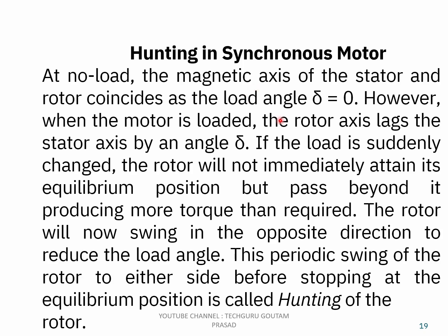So what is hunting in the case of the synchronous motor? At no load, the magnetic axis of the stator and the rotor coincides as the load angle delta is 0. However, when the motor is loaded, the rotor axis lags the stator axis by an angle delta. And if the load is suddenly changed, the rotor will not immediately attain its equilibrium position, but pass beyond it.